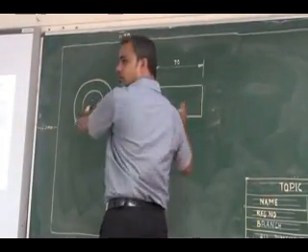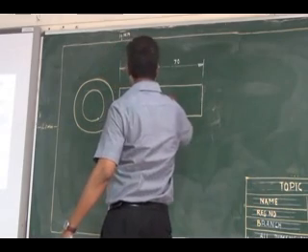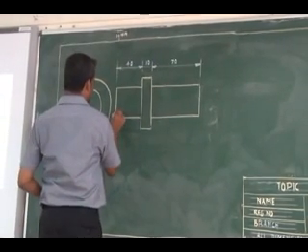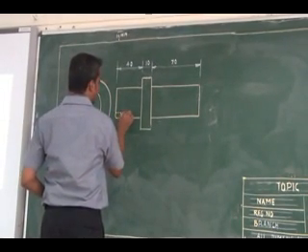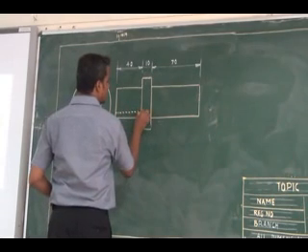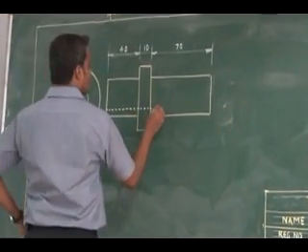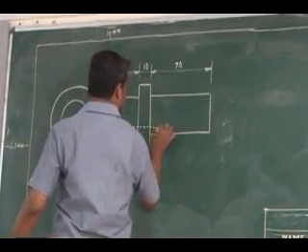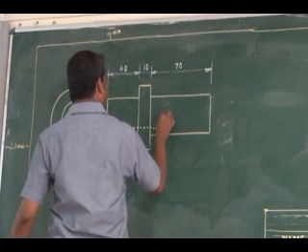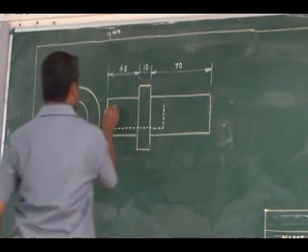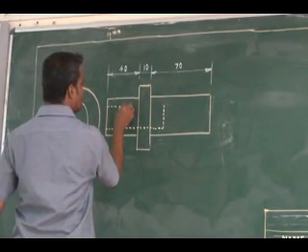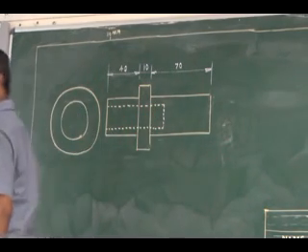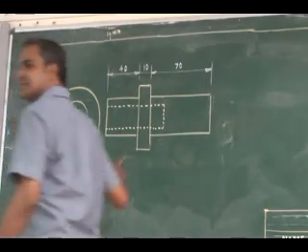In this front view, there is a hollow portion here, going through to some distance. I can represent it as a dotted line. See, it is a hidden line. What pencil are we using? A sharp pencil. So up to this distance it is hollow throughout. Is it clear?